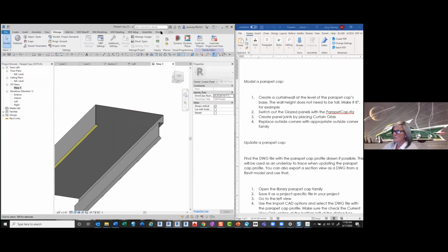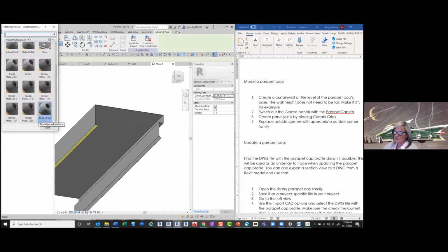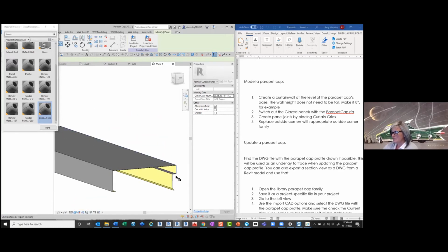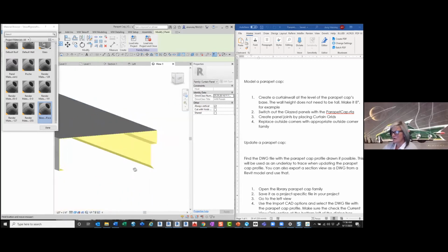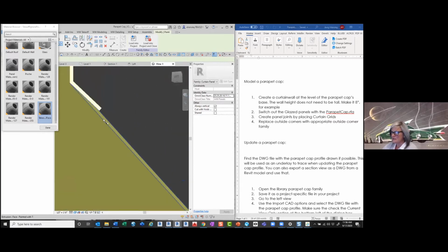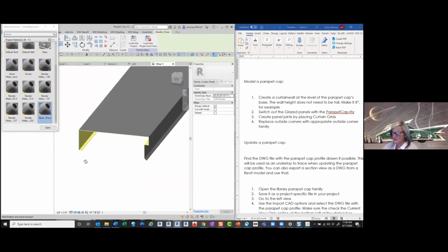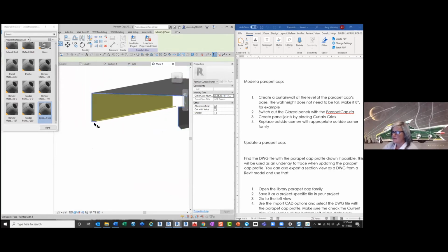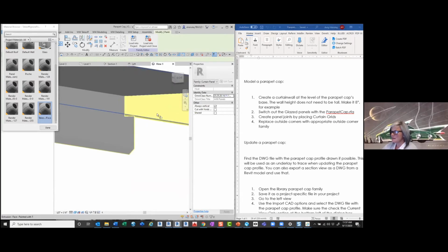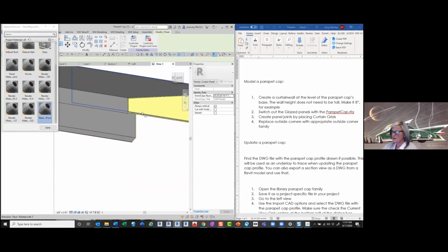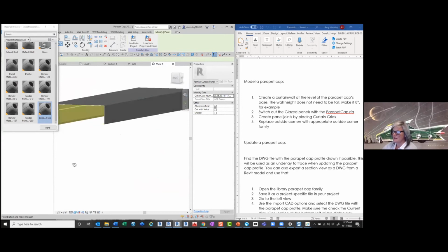So anyway, we go back to Modify, Geometry panel, Paint tool, and select Takeoff Ignore Panel Face, all the way at the bottom. As long as it's highlighted, that's current. And you just start picking surfaces. So I'm picking all these interior surfaces that I don't want the takeoff program to read, including this little back edge down here. It started out yellow, but when we modified the part, it went back to the default material. So everything on the inside and both end edges should be the yellow material. And all these other pieces of data will get picked up by the takeoff program.